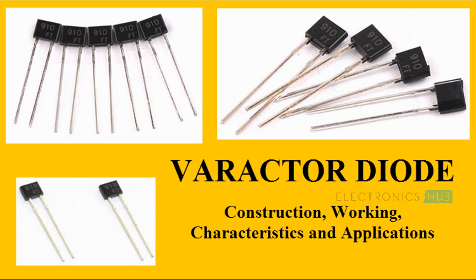Key characteristics and concepts of voltage-controlled oscillators, VCOs, include: 1. Frequency tuning. The primary feature of a VCO is its ability to produce an output signal with a frequency that can be varied by changing an input voltage. By adjusting the input voltage, the VCO's output frequency can be tuned over a specific frequency range. 2.